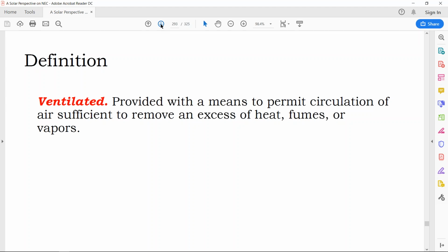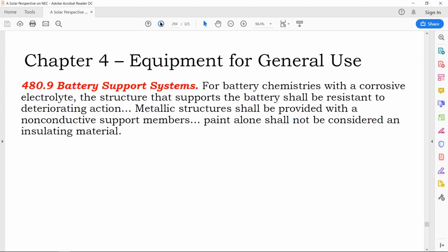What you will typically do is put a hood over your unsealed batteries and vent them directly to the outside. And the gas is lightweight in a battery room, so it'll rise up into the hood with a small fan for continuous venting.